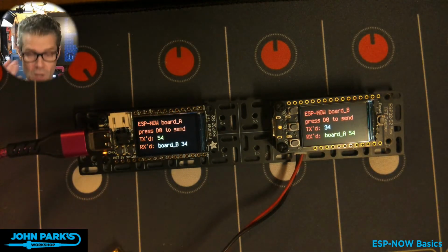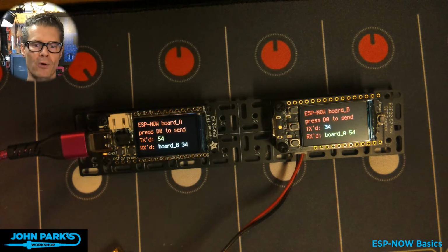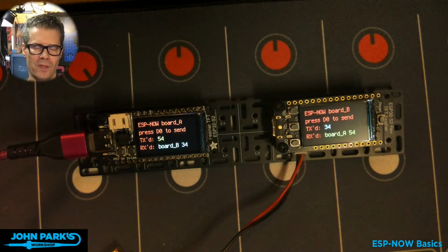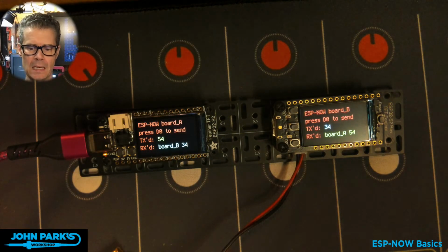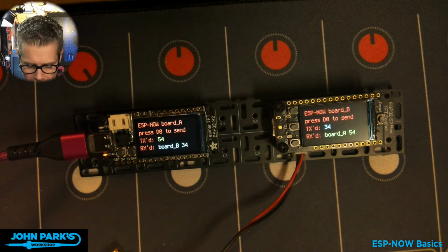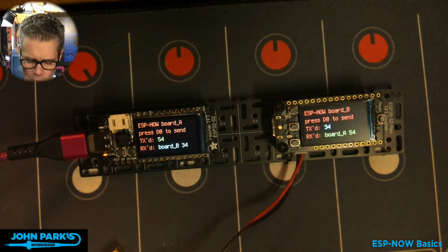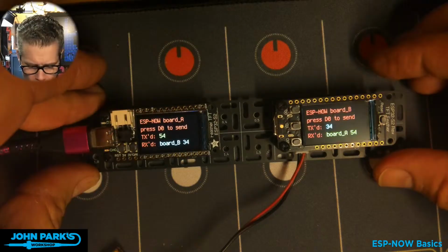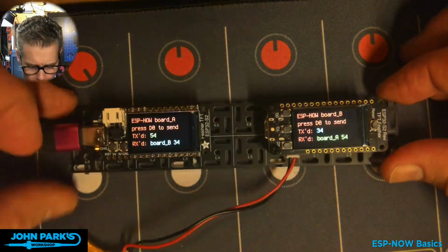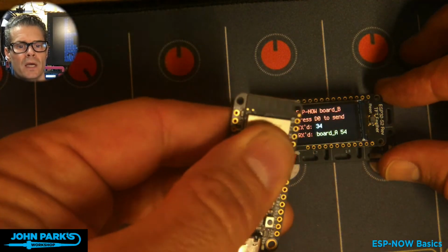As I've talked about ESP-NOW a little bit, ESP-NOW is connectionless, does not use a hub, does not use a Wi-Fi router, does not use a lot of the stack and a lot of the things that can benefit computers doing complicated things, but can slow down microcontrollers doing simple things. Sends up to 250 bytes, a small little packet. Sends it really fast, and it sends it 100 to 200 feet in the open air. So it's got a nice range to it, and that's just with these little onboard antennas like this one you see here, this little PCB antenna, that little squiggly there.